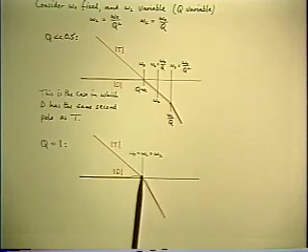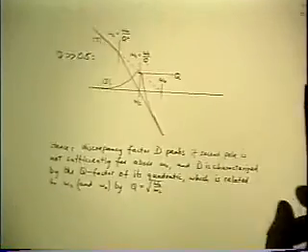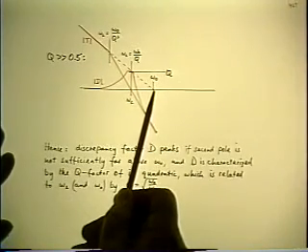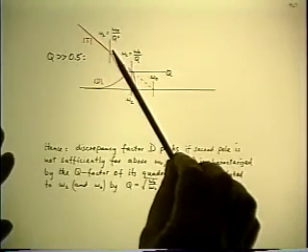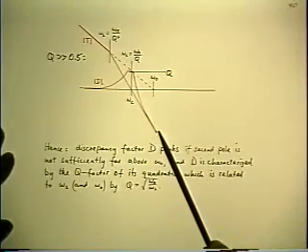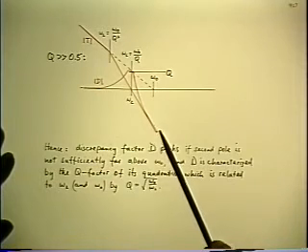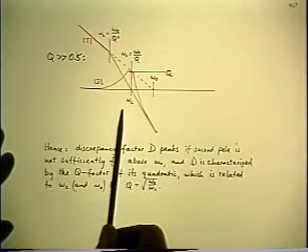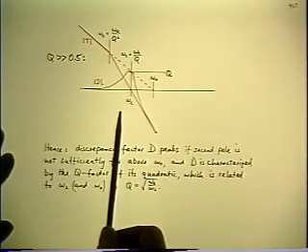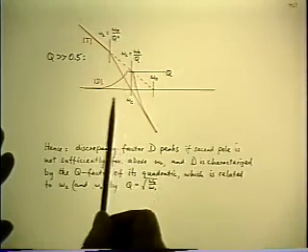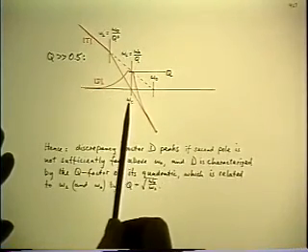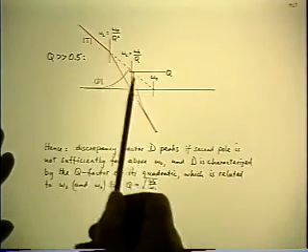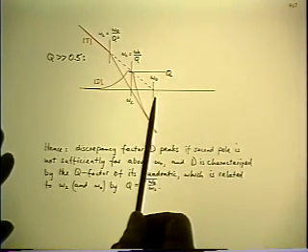Well, what happens if you go to an even bigger Q, which is what happens if the second pole in T comes in even before the original crossover? So now you're crossing over on a double slope. And now the quadratic representing the closed loop response D peaks up significantly for a high Q. And the geometry is such that at the corner frequency of the quadratic, the closed loop response actually goes through the point that lies on the asymptote of the original slope.